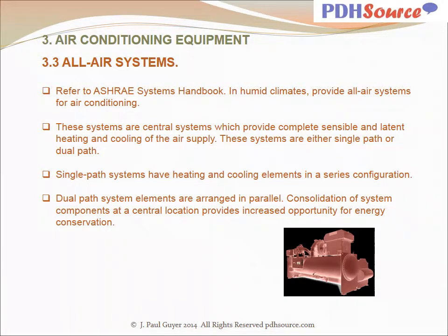With regard to all air systems, refer to the ASHRAE Systems Handbook. In humid climates, provide all air systems for air conditioning. These systems are central systems which provide complete sensible and latent heating and cooling of the air supply. These systems are either single path or dual path.